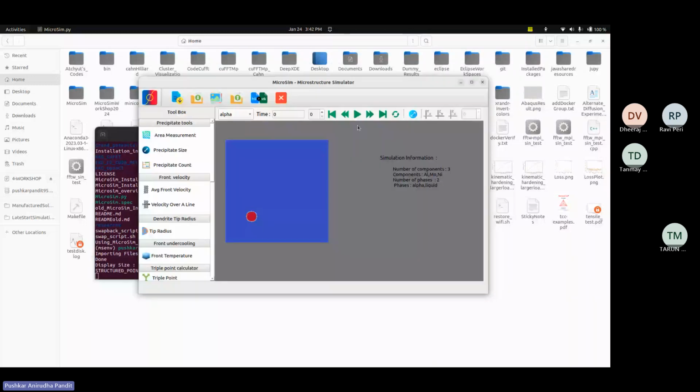If we run it, what this file contains is the undercooling of all the phases for your models. You see that halo around it, that is essentially spreading. That halo around it is essentially showing you that the interface becomes diffuse. Typically that is not a good sign. That means the undercooling that you have given for this particular problem is too large for the delta X. Reduce the undercooling to 50 Kelvin and see what happens before running the CUDA file.